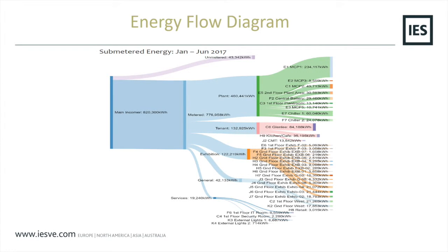So within the museum, what we found is the existing energy team in the building, they were scurrying around, let's replace the lighting, let's put in LED lights on the exhibits. You're never going to save any energy when you do that, when your big users are heavy energy hungry. So we would say, pick mechanical panel 1, find the plant associated with mechanical panel 1, and obviously target your energy saving interventions on that area. Otherwise, you're just wasting your time. So retro engineering done right, you can really target where you need to spend the money and your effort.